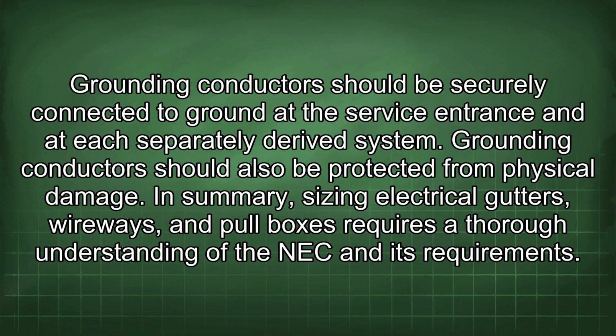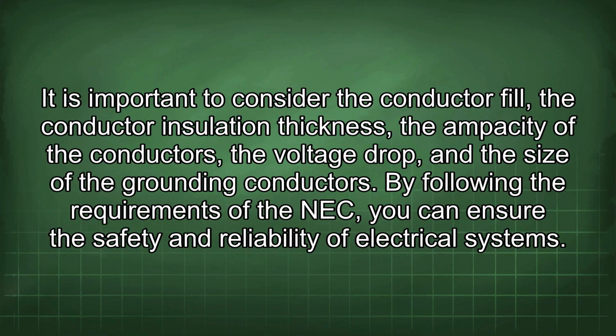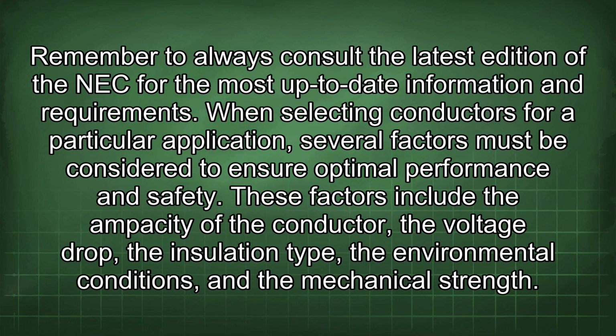In summary, sizing electrical gutters, wireways, and pull boxes requires a thorough understanding of the NEC and its requirements. It is important to consider the conductor fill, the conductor insulation thickness, the ampacity of the conductors, the voltage drop, and the size of the grounding conductors. By following the requirements of the NEC, you can ensure the safety and reliability of electrical systems. Remember to always consult the latest edition of the NEC for the most up-to-date information and requirements.